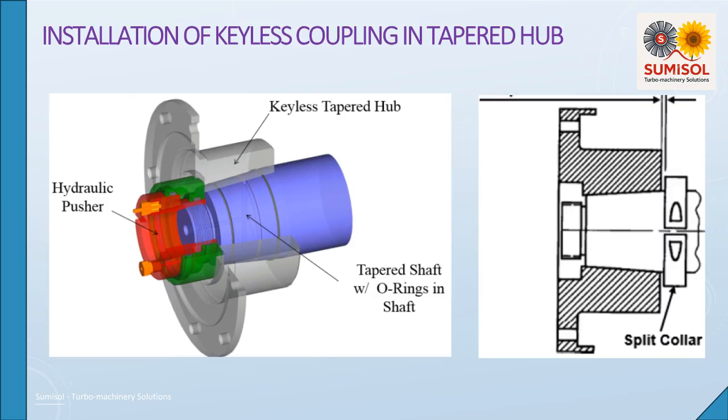Tapered bores for keyless, hydraulically fitted hubs shall have at least an 85% blued fit surface contact to the taper gauge. Improve the contact. If less than 85% contact is found, the shaft and hub should be independently lapped using a ring and plug tool set. Clean the lapped surfaces. Remove all traces of lapping compound using a solvent and lint-free towels. Immediately afterward, spread thin oil on the shaft and hub bore to prevent rusting. Recheck the hub to shaft contact.